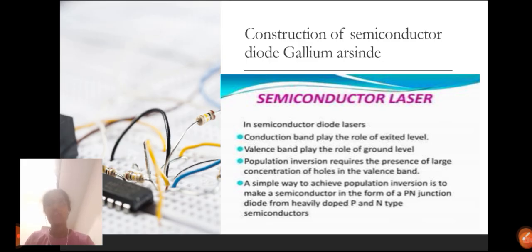Semiconductor laser material has two criteria. First, a direct bandgap semiconductor is used as the active medium. Second, the semiconductor is a degenerate semiconductor, where P-type and N-type are heavily doped, which is beneficial for achieving lasing action. If both criteria are satisfied, the compound is called gallium arsenide. Gallium arsenide is the earliest semiconducting device.